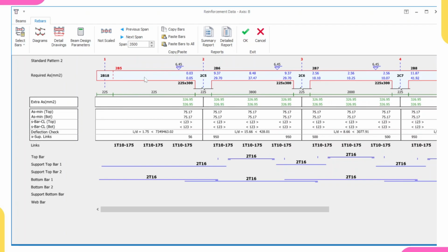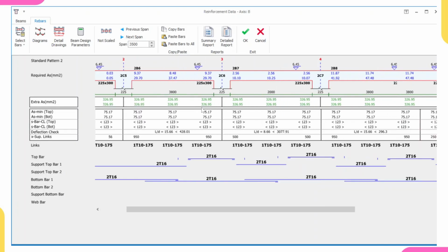Look at what you're having. The area of steel required is 0.09, so it's too small. Normally I don't apply hinges on my roof row. Also look at the area of steel provided. It is 300 and something. Why, in story 1, the area of steel provided is even 200 and something, so the area of steel here is even more.